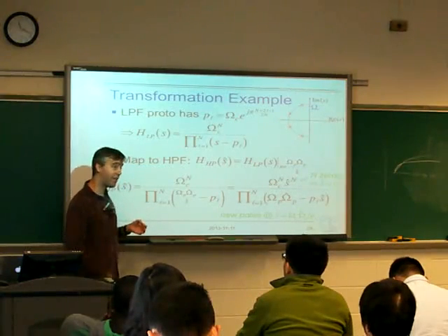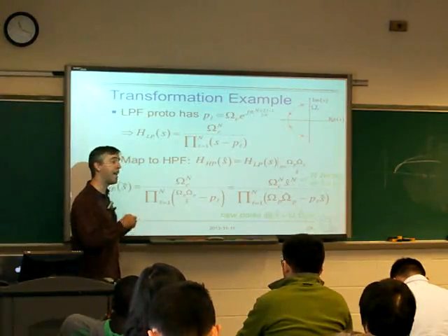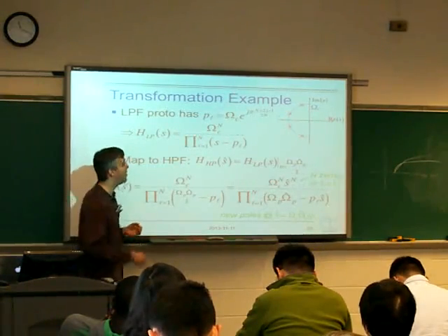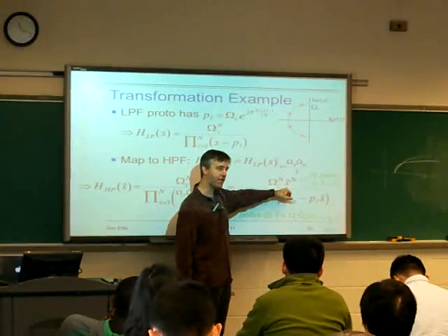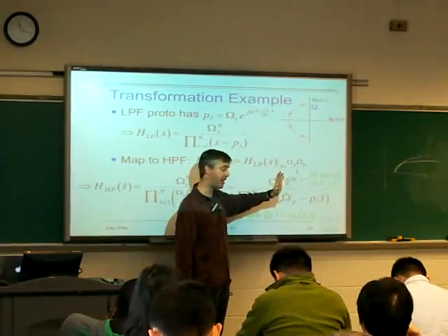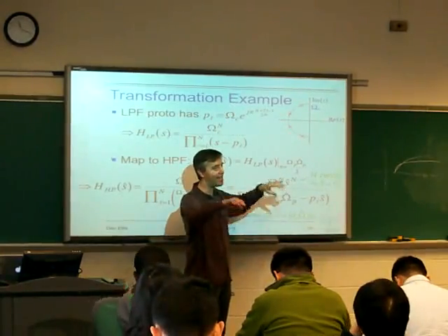It's a Butterworth high-pass filter, so it's smooth, but its gain probably is going to go to 0 at 0. So yes, this Butterworth filter has a stack of zeros at frequency 0, so at frequency 0 it really does have a gain of 0, but they're all the same place, so they grow uniformly.